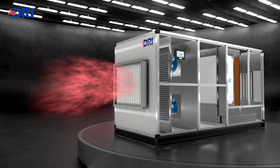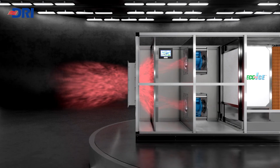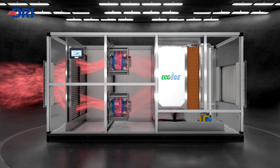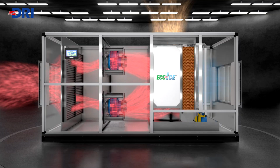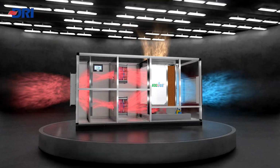In the first stage, the heat exchanger ensures the air is pre-cooled without adding moisture. This lowers the air temperature significantly before it enters the direct evaporative stage. Since the air is already colder before reaching the water-saturated pads, it undergoes a second cooling phase that pushes it below the wet bulb.